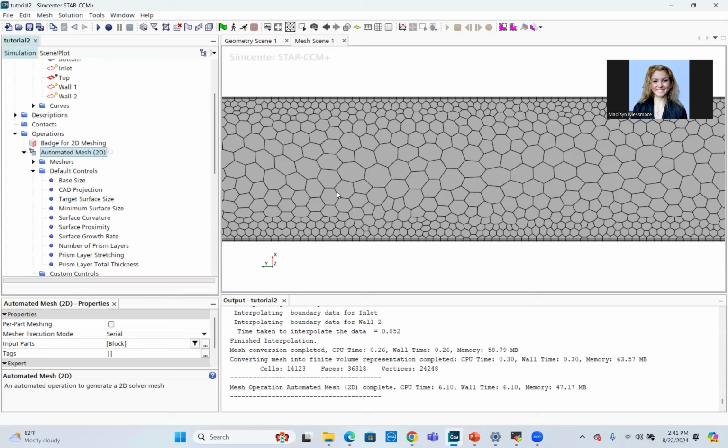So in theory, the smaller your mesh cells are, the better detail you can get. However, the smaller they are, the more calculation you have to do. So there's the trade-off: how much detail do you actually need versus how much power and time you have? There's the trade.